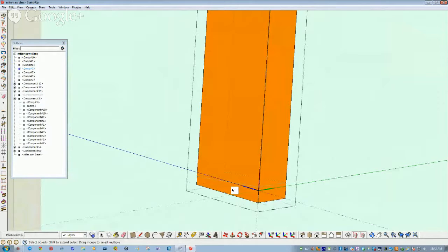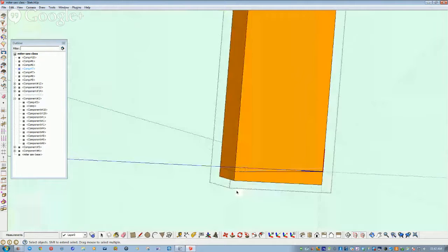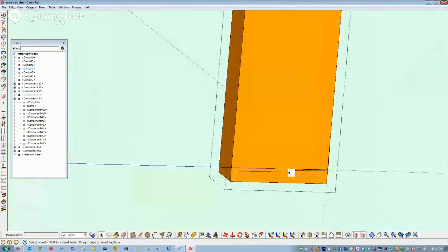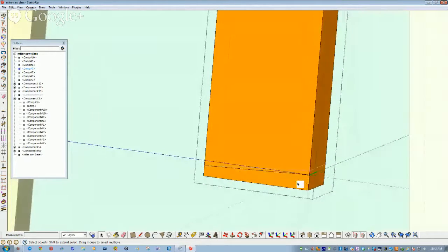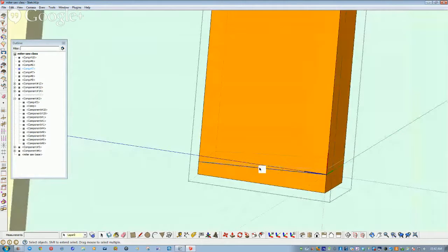Now, what you just saw me delete was a line element that it created where I didn't want it. I'm going to Control Z and put it back in. What happened when I was making this line is it decided it wanted to lock onto the origin of the part rather than the intersection up here. You have to be careful with that. With any CAD program, you have to be careful. You've got to learn its priorities. Otherwise, you'll get things off just ever so slightly.